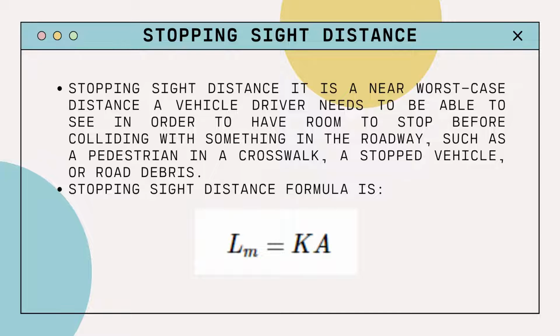Without this table from AASHTO, curve length can be calculated. Formulas have been derived to determine the minimum curve length for required sight distance for an equal tangent curve, depending on whether the curve is sag or a crest.